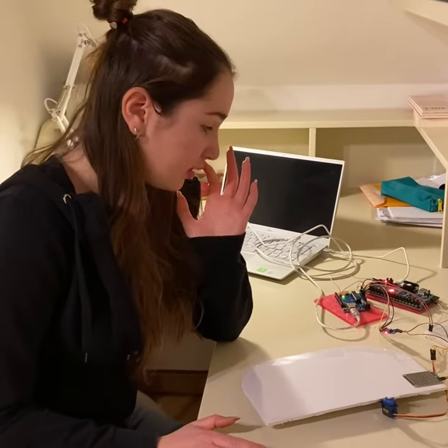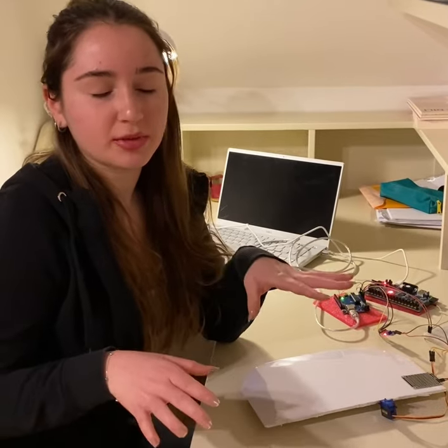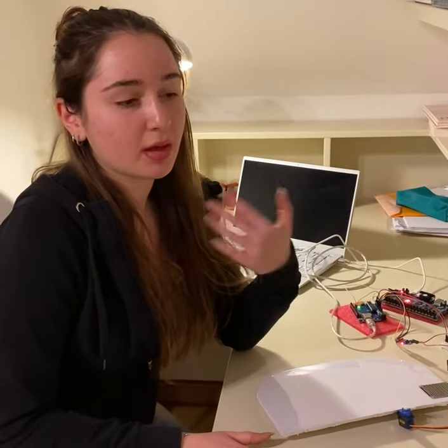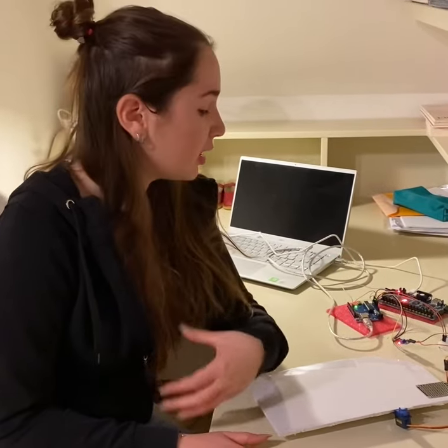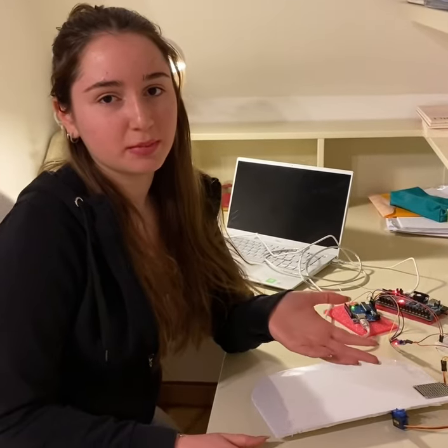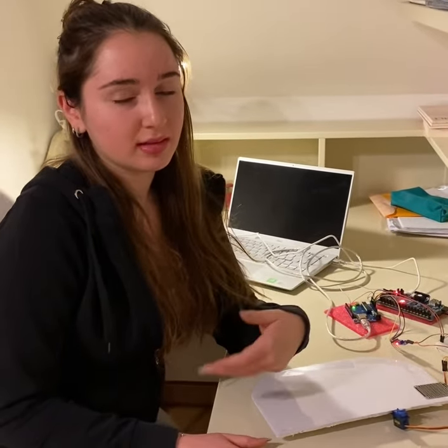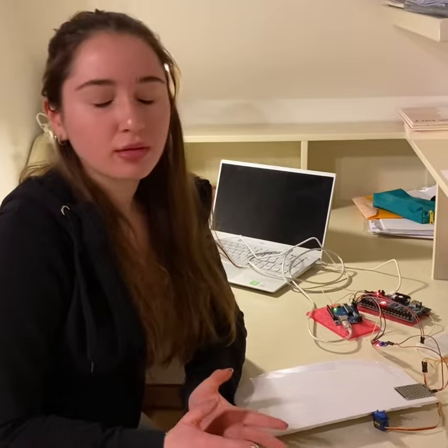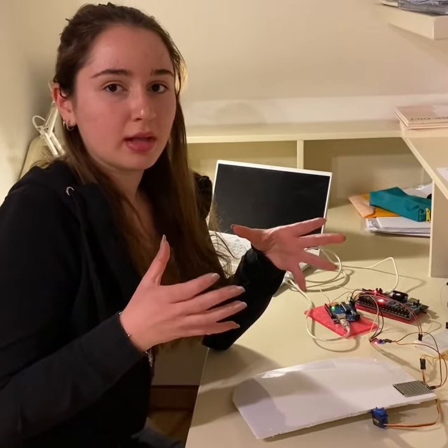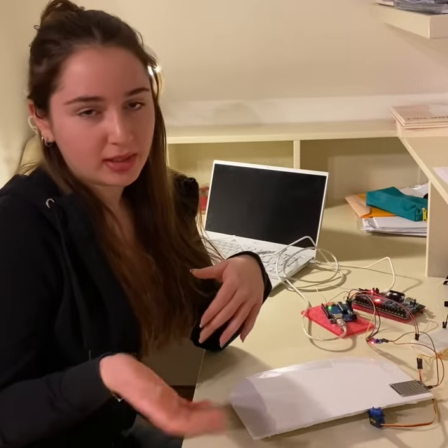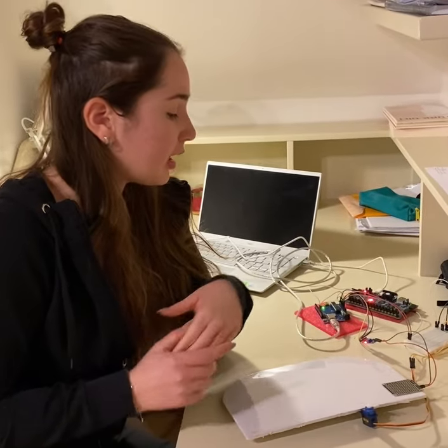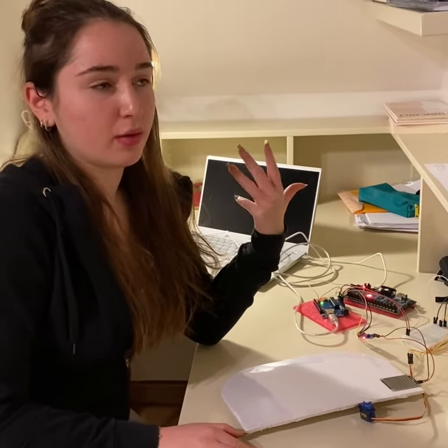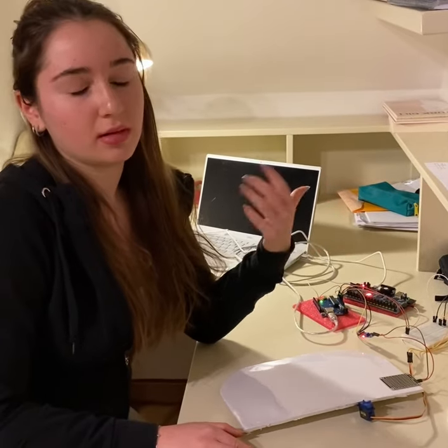In Arduino, I did this project in two separate parts and then combined those two. For the first part, I gained analog signals from the rain detector and converted them to digital signals to use in my project. I use analog signals because I needed the amount of water so that I can change the wiper's speed. I did the conversion on Arduino and then took those signals and used them in the Basys 3 FPGA.